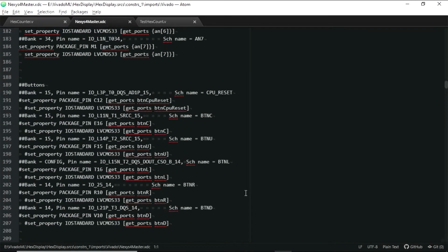So get your XDC from your board maker, whoever that might be, because without this you're kind of lost as to what's connected to what. You've got to get out the logic probe and write a program on the FPGA to go and turn on and off each of the LEDs or each of the outputs. You know, it's such a headache.